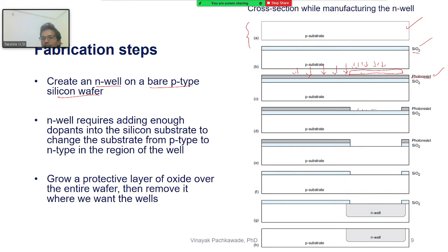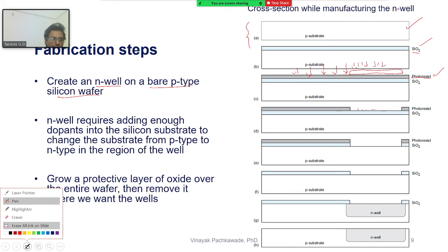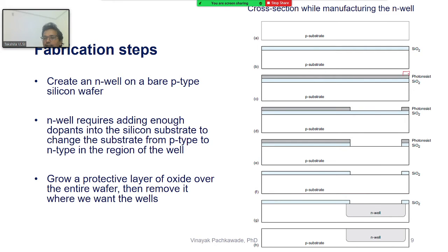If you are using the positive photoresist, they put the mask here, and then the system is exposed to the UV light all over. The portion where the mask was present, the light did not reach the photoresist, and the remaining portion where you did not have a mask, the light reached, and this particular area got away. The photoresist got melted, softened away. So you got rid of it here.